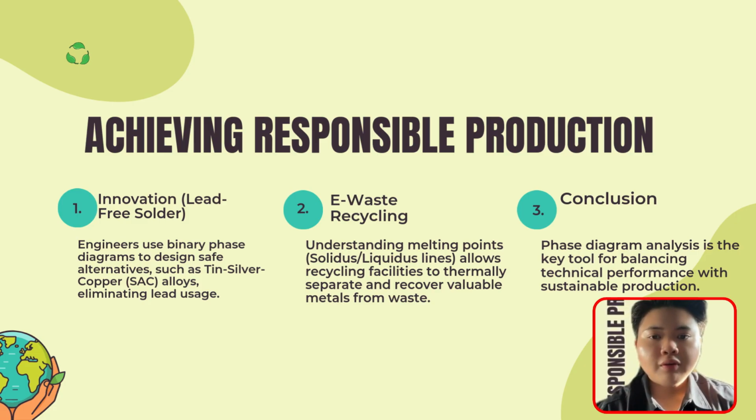So, how do we resolve this conflict? This brings us to achieving responsible production. The knowledge of binary phase diagrams is actually the key solution here in two ways. Number one, innovation. Engineers use binary phase diagrams to design safe alternatives, known as lead-free solder, such as tin-silver-copper or SAC alloys. By studying the phase field, we can replicate the good properties of lead solder without using the toxic lead itself. Number two, e-waste recycling.